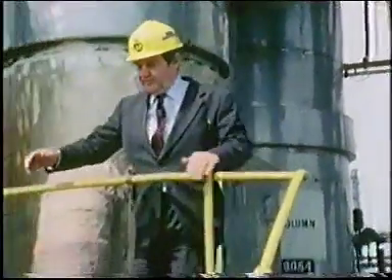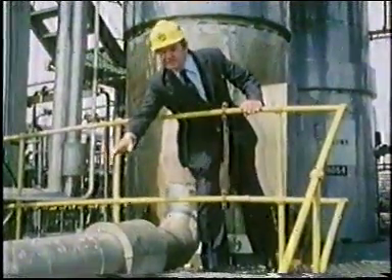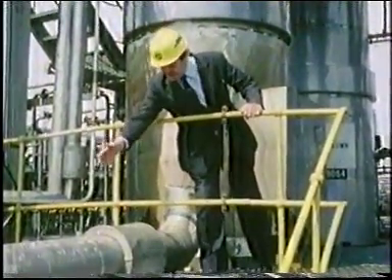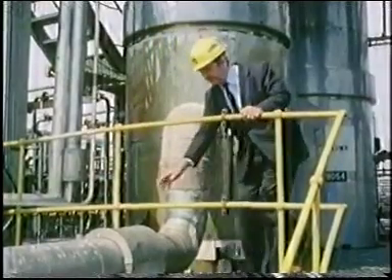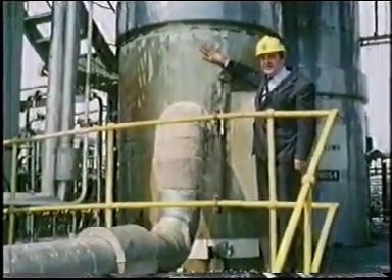Distillation is a complicated separation process, and very often it is difficult to obtain a pure component in a straight distillation. In our reaction here, we do have a mixture of an ester, an alcohol, water and an acid, which is non-ideal. However, in this case, the non-ideal behaviour enables us to design a relatively simple and efficient process to give pure ethyl acetate. As John said, the vapour from the reaction system, which contains the manufactured ethyl acetate and water and acid and a bit of alcohol, comes along this vapour line into this distillation column.